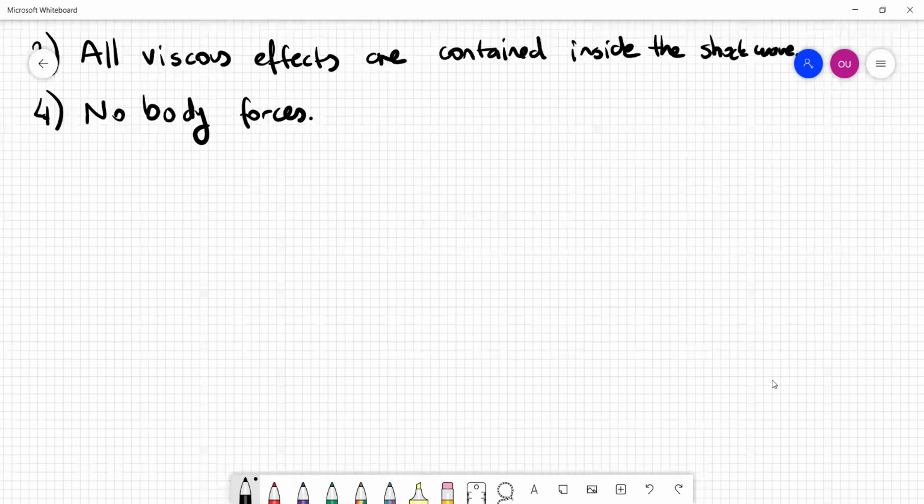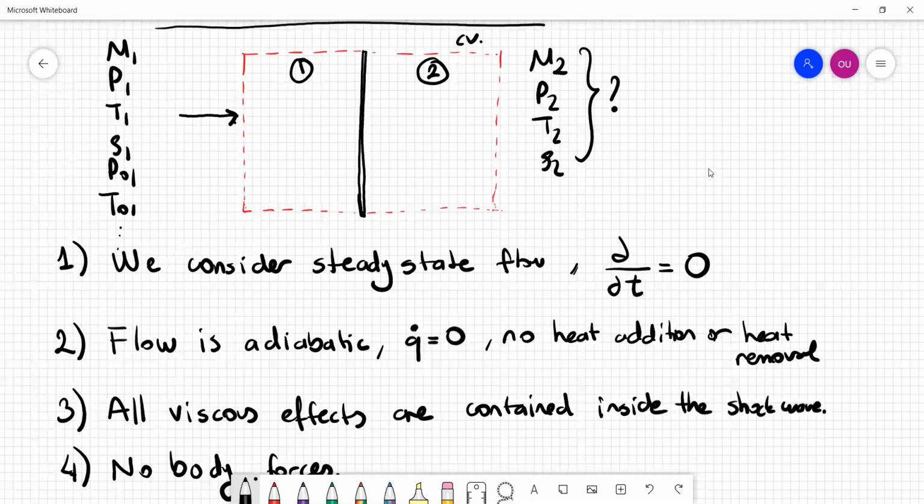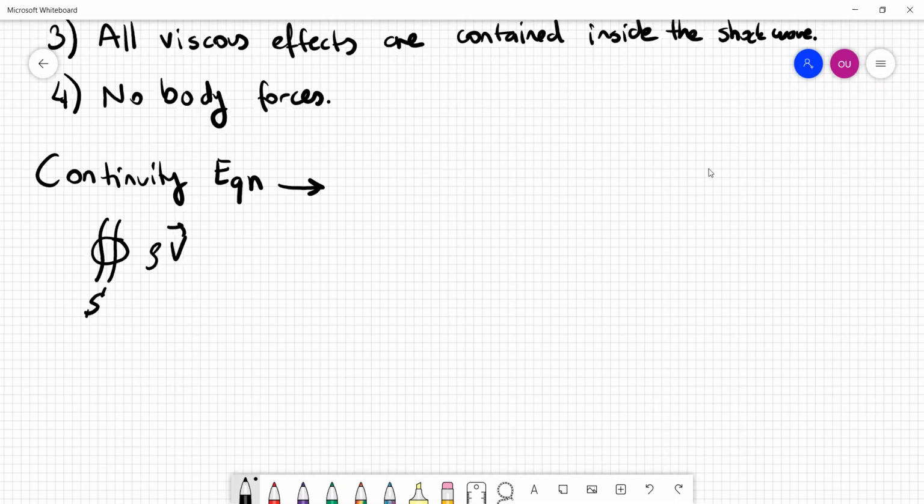So we were discussing this control volume analysis. This is our control volume, and we start with our continuity equation, so mass conservation. Let's first talk about this. Of course, first of all, we assume this is a steady state process, so we lose the first term. If you remember, we talked about these terms last week. If it's in that video, you can rewatch it if you don't remember. So we only have the surfaces. The mass flow incoming and outgoing from the surfaces, that balance is designated by this integral equation.